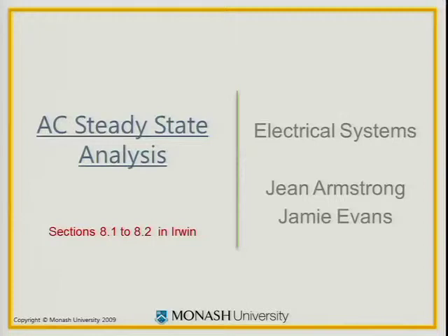And it turns out that even if we have lots of capacitors and lots of inductors, with a little bit of a magic trick, all of the circuit analysis techniques we've used so far, certainly KCL, KVL, they apply, nodal analysis, mesh analysis, we can just do it all again, even though we've got capacitors and inductors and sinusoidal sources. The magic trick is going to be that voltages and currents will be complex numbers.